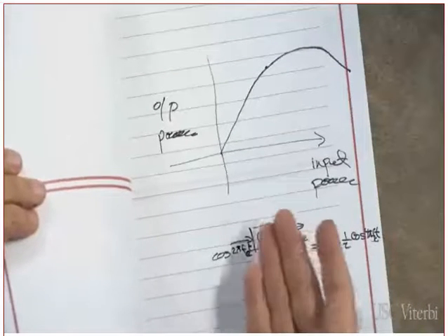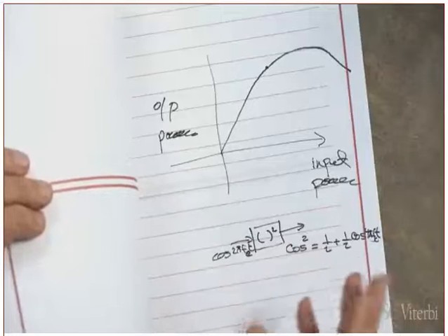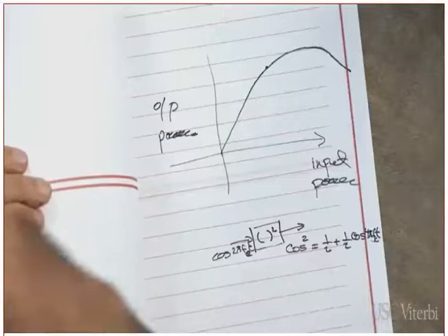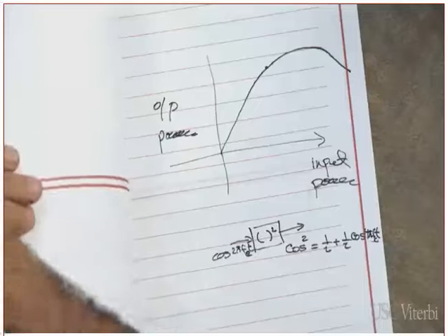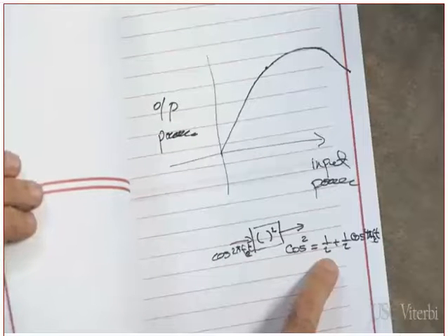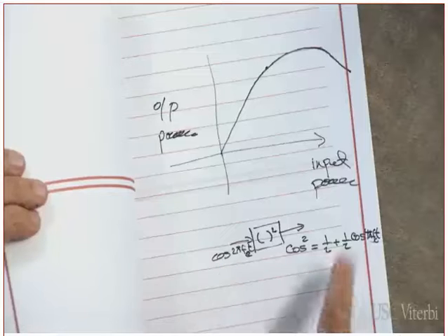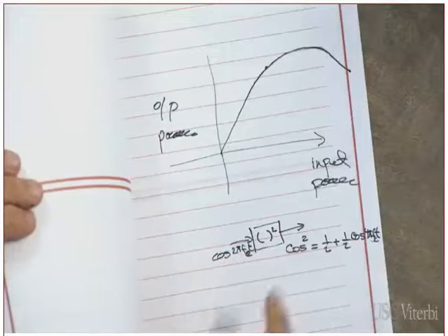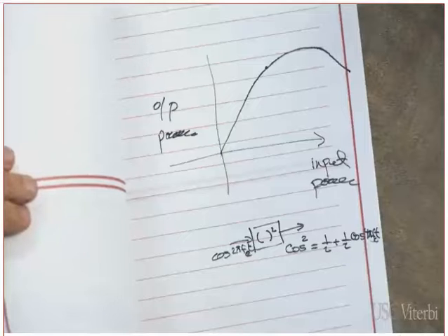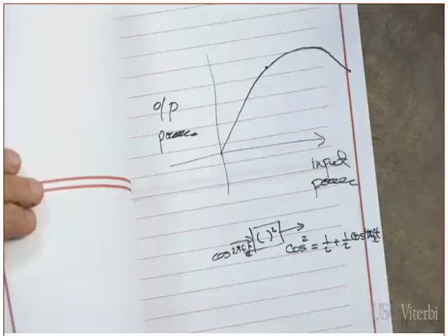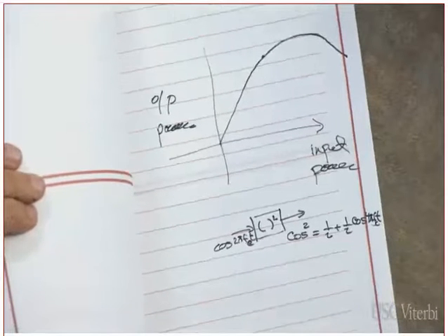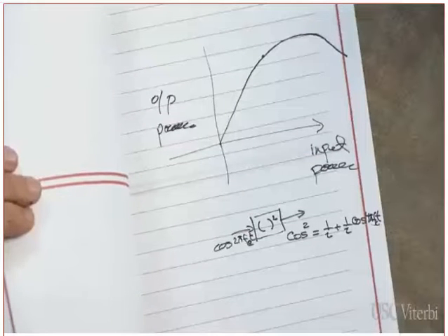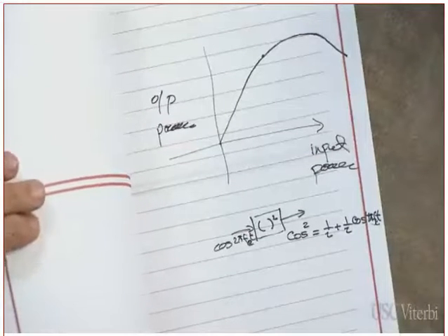Clear? This is just to show you how you know that the system is linear or nonlinear. A nonlinear system creates frequency components that were not available at the input. Is there a DC component at the output? Was there a DC component at the input? No. It created a new frequency component. Was the second harmonic present in the input? It created it at the output. Clear? A linear system may amplify some frequencies, may reject some frequencies, may attenuate some frequencies, but it does not create new frequency components that were not available at the input.